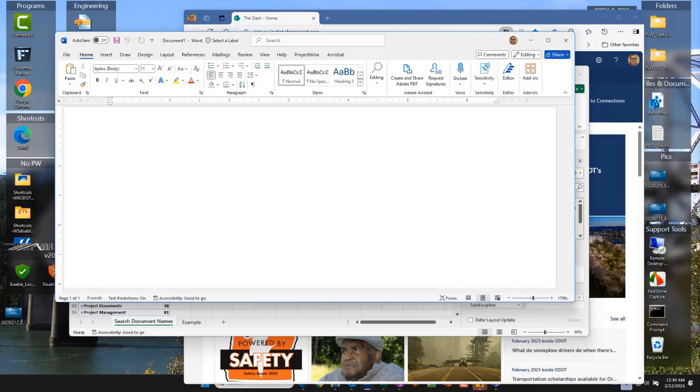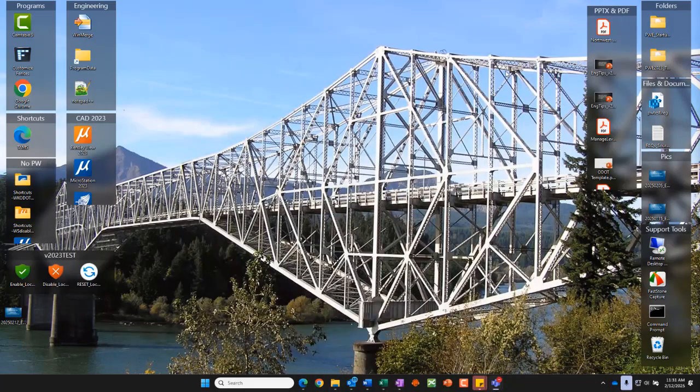I do see a chat. I think what's being asked is, how about 2 sessions of, say, MicroStation? No. At ODOT, we never recommend that you open 2 sessions of MicroStation, each showing a different drawing, because that's the pathway to corrupting your preferences. So we don't recommend that at all.